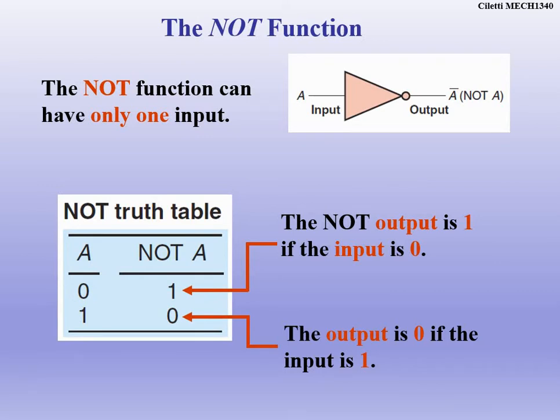We're using an inverter. So this is a 74LS04 chip when we do breadboarding and things like that. Okay, so this is the NOT function. The AND, the OR, and the inverter, the NOT gate, are all the fundamental logic gates for what we use. Now, a lot of the logic gates that we use in your phones and computers are all built from NAND and NOR gates. We'll get into those a little bit later on. But these are the foundation and the fundamental logic gates so that you can start understanding thinking logically to be able to program things logically.